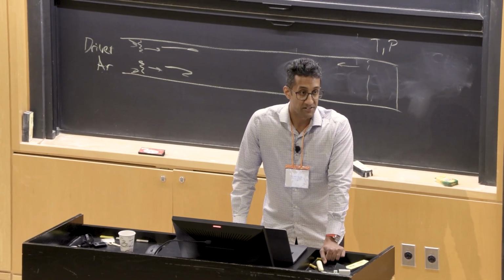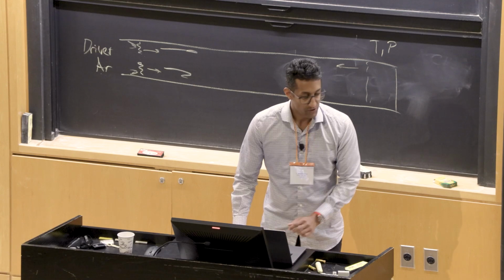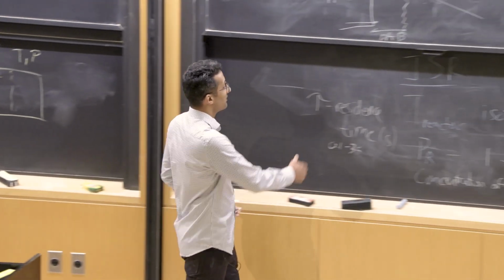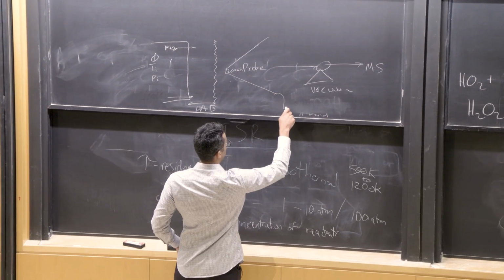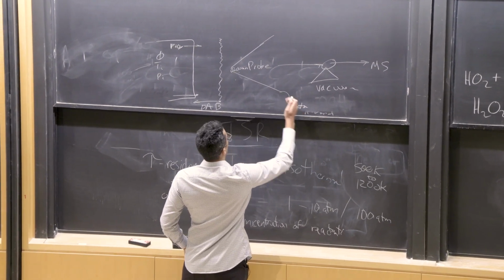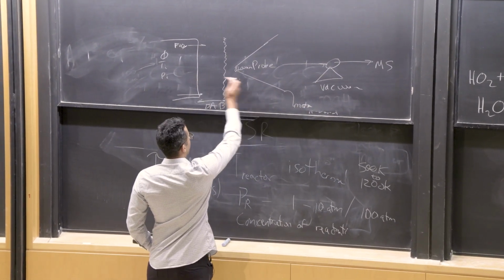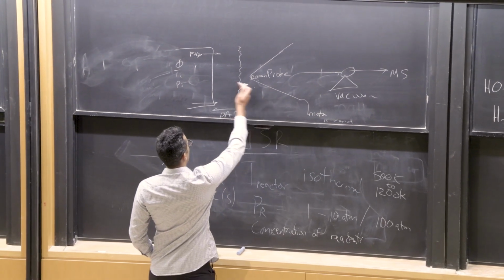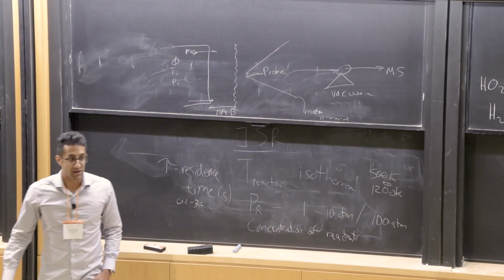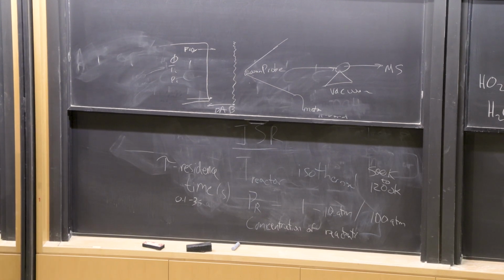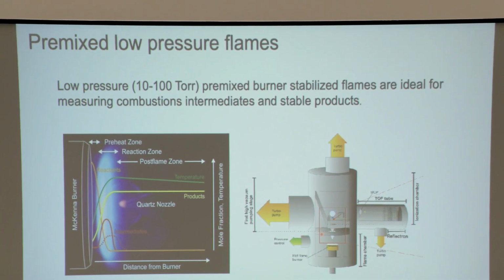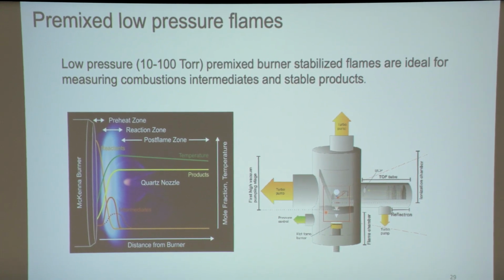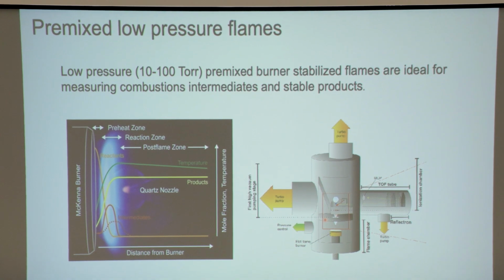And if something breaks inside, like you translate this cone, okay? This cone is connected to some kind of a motor, so it can move towards and away from the burner surface. And if you move it too close, like I've done many times, you break the cone. Yeah, then what you do, if you break the cone, you gotta rip apart the entire rig, depressurize it, or repressurize it, take it apart, change the cone, and you lost 1 day of experiments.